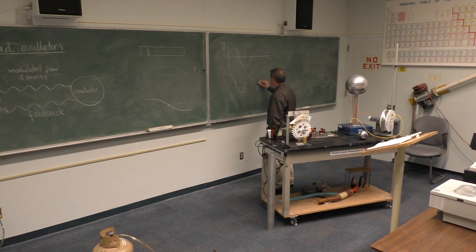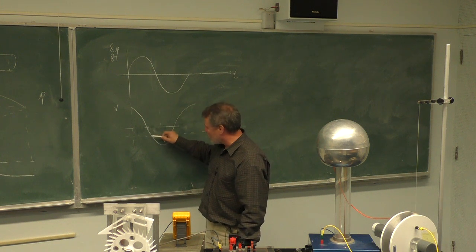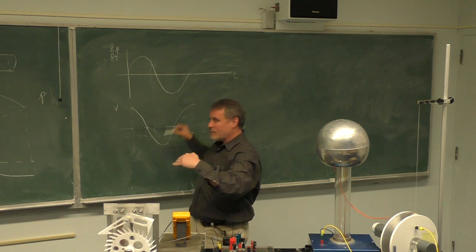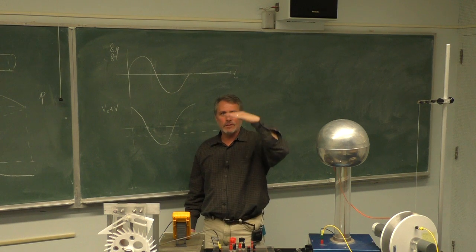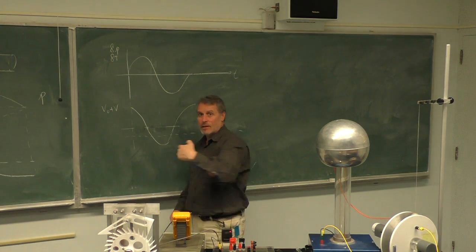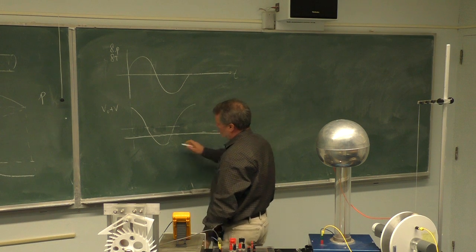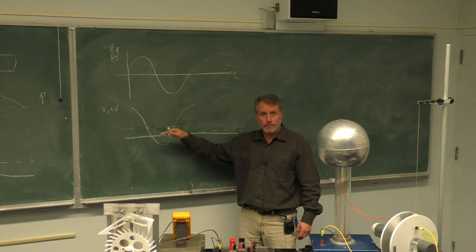And so that means that I have to superimpose to this velocity a DC flow. So when I superimpose a DC flow, that is what is happening to the velocity, right? The nodes of the velocity don't happen here anymore, perhaps they happen lower because now I have a superimposed DC flow. So if you add this cosine function a constant flow in the same direction as the velocity swing, then you are raising the overall thing relative to the zero line, right? So the velocity nodes are there, but they are not there anymore. Okay, so you raise that. Is that clear?